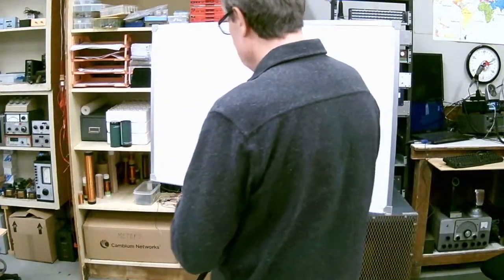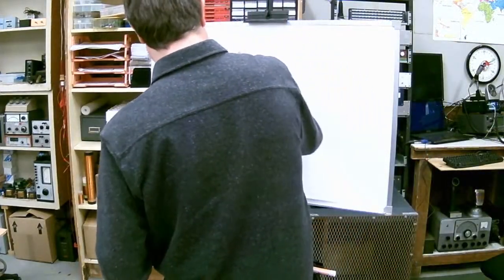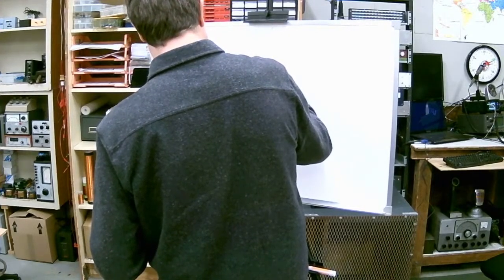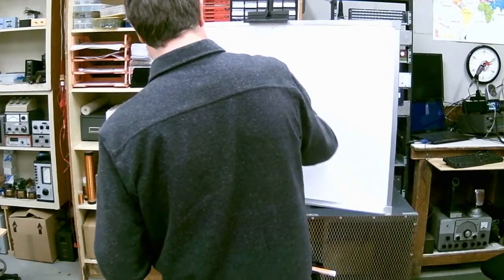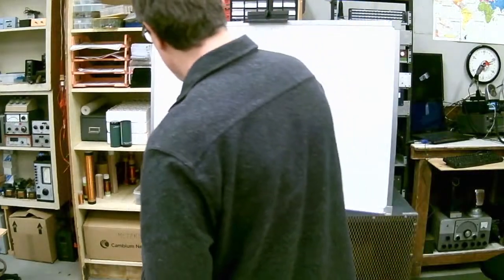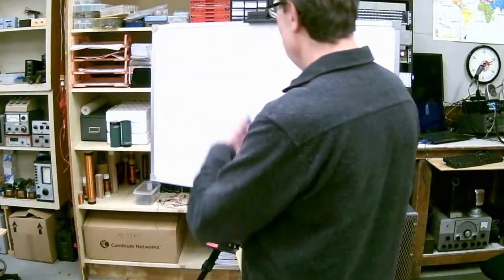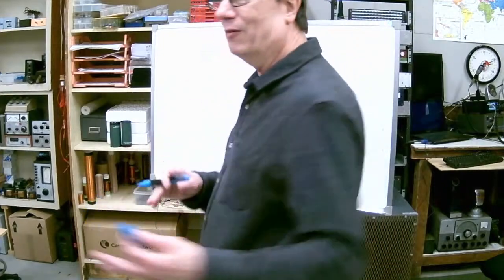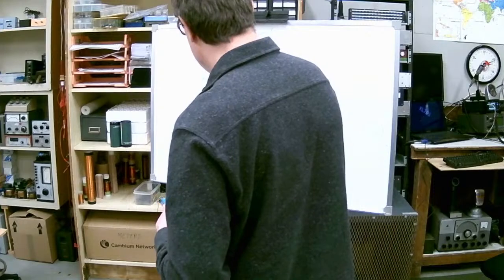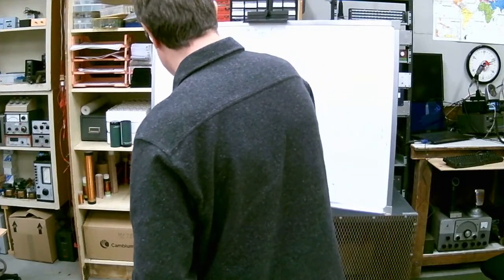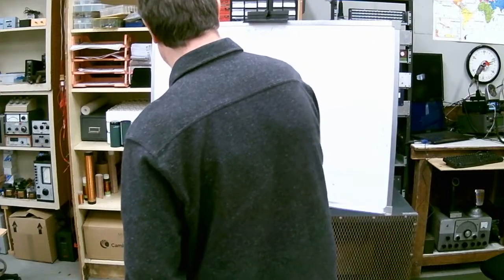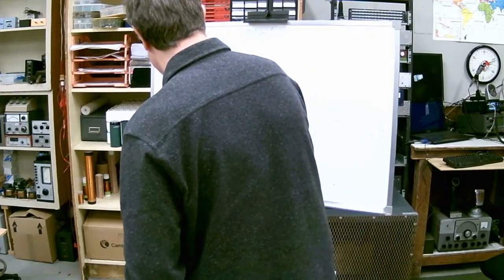Take a high IF frequency of, let's say, 1600 kilohertz. I'll just draw a square here that includes all the amplifiers that are tuned to 1600. The local oscillator would be 1600 above whatever you have coming in. So this would be a much higher frequency. So what would you want to do? Let's say I'll use the same frequency here, so we'll tune that to 2600.